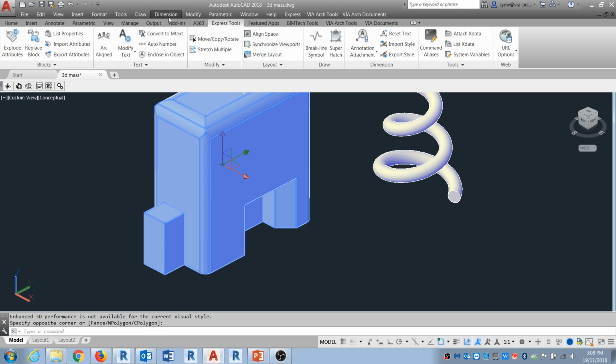One thing I like about the AutoCAD side of things is that the massing is actually a 3D solid if you use Extrude. So it's the same concept as using Revit. When it translates into Revit, it's already translated as a massing, so you're not going to lose anything as you explode it. Whereas if you use SketchUp or Rhino, it may use some other stuff, which I'm not sure how it's going to be. But I know that AutoCAD to Revit will produce a much better, cleaner result for the massing.